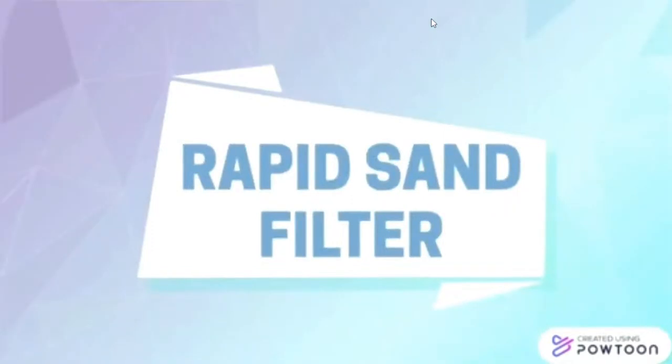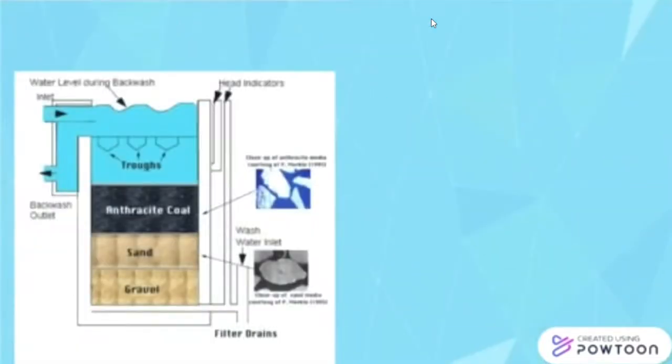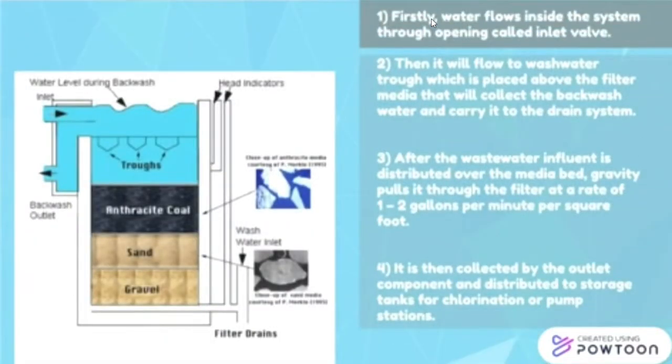The next part is, we will learn how a rapid sand filter works. Rapid sand filter is another type of water filter which operates at a higher rate, about 25 to 50 times faster than a slow sand filter. The first step is water flows inside the system through an opening called the inlet valve.